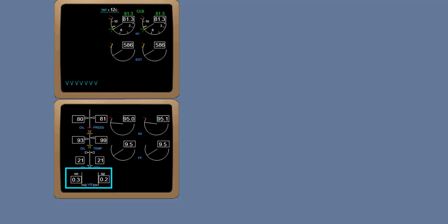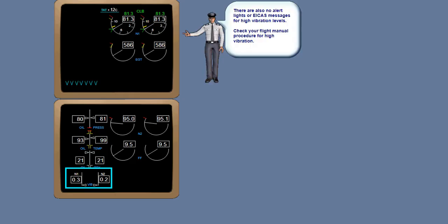The last set of gauges of the secondary engine display are the engine vibration monitors. These monitors are primarily intended for engine condition monitoring, but can also be used to isolate engine anomalies and to take corrective action. Normally, the crew will reduce the engine RPM if high vibration is detected. Consult your flight manual for this situation. Also, remember to consult the cold weather operations section in the event of ice accumulations on the engine blades.